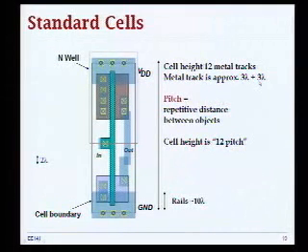So now in our technology, that is 0.75 times 12, so it's about 9 microns height for the standard cells. And now you see all these contacts, for example, to VDD. So when you flip over the mirrored cell and put it next to each other, you will basically exactly put the wells next to each other. You will have all these shared contacts, and basically everything nicely fits together.